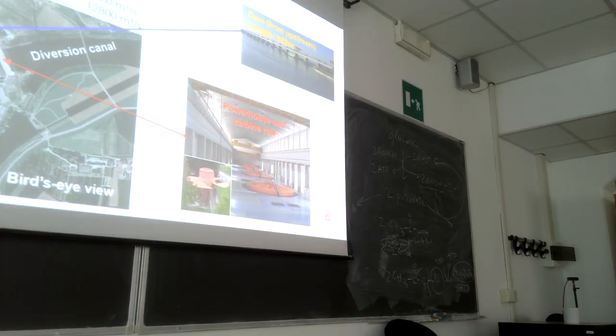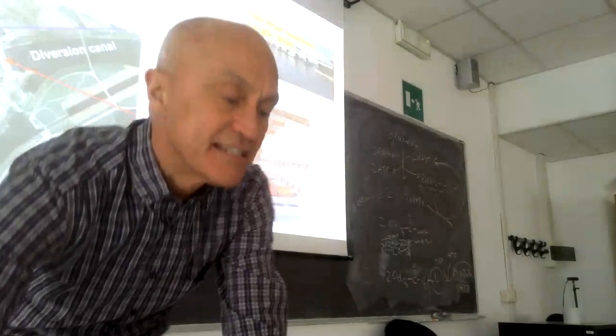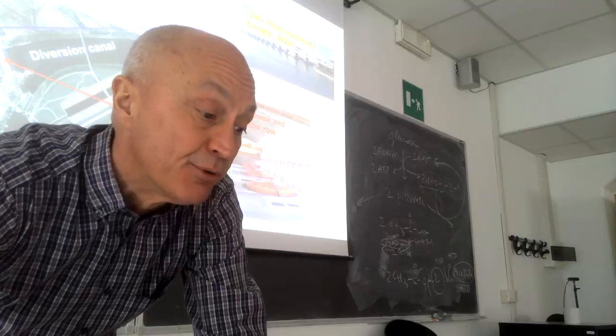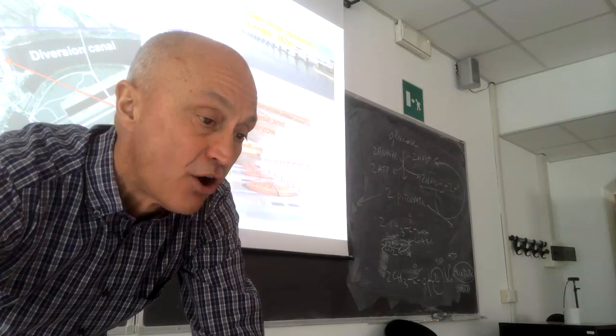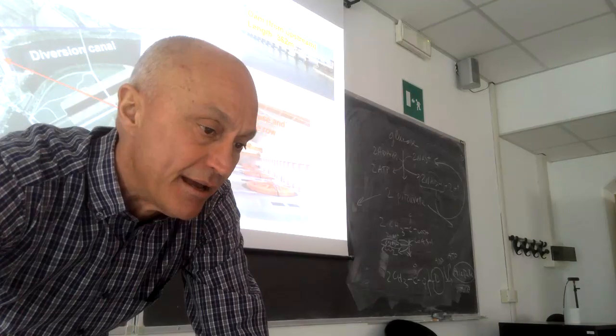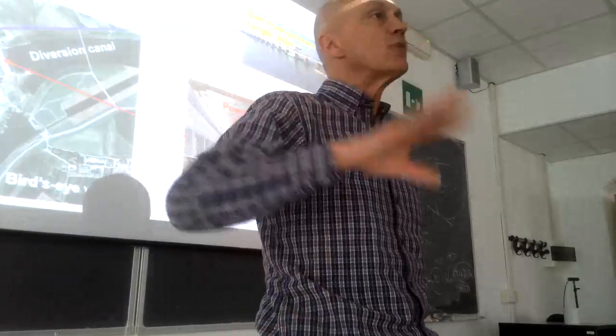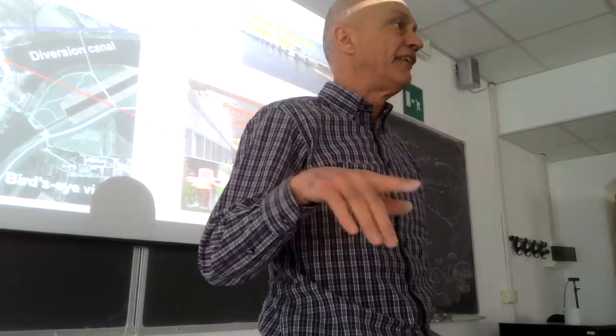Very good. This is instead a hydrologic feature. The River Po historically had a maximum discharge at this point of almost 13,000 cubic meters per second. Of course, when there's a huge flood with a return period of 50 years or above, the power plant is closed because there are all sorts of sediments traveling with the discharge, so they do not produce energy during a very major flood. They can use minor floods to produce energy.